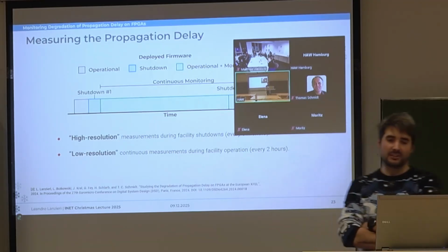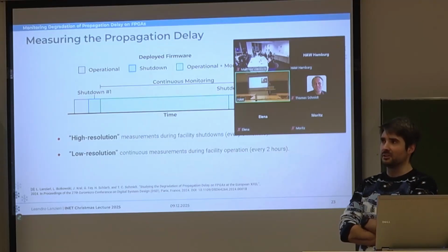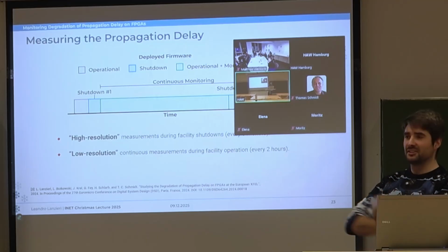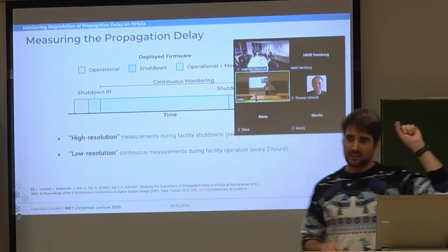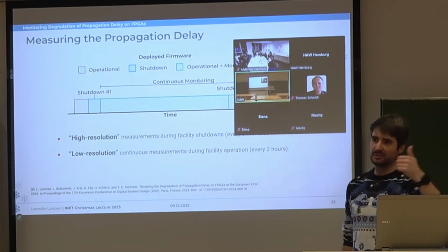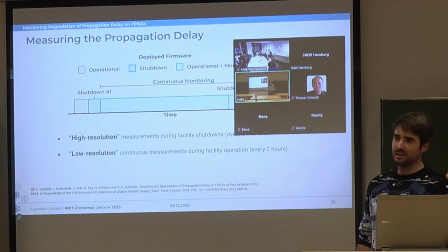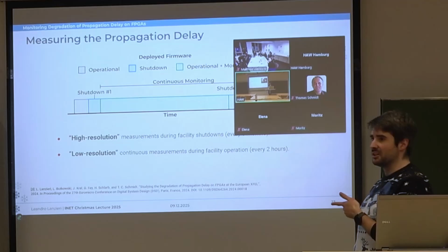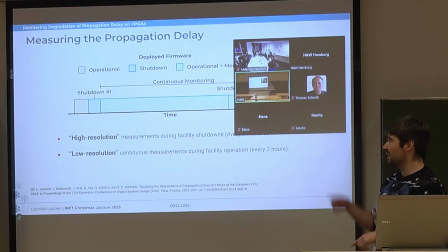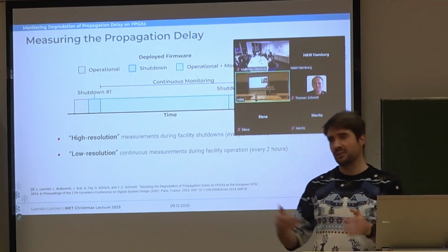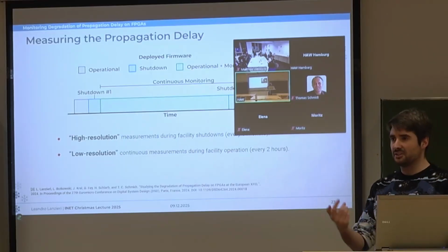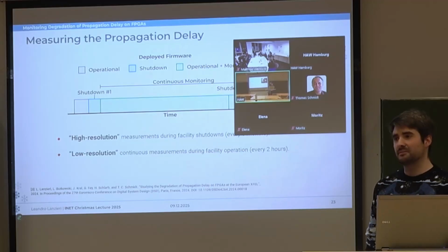Not, I think I understand. And I think if you actually look with a microscope a bit, or more like from far away, this is what we did. If you remember the beginning of the talk, I talked about threshold voltage, and that's actually been the constant across all of the things, because in the SRAM we observe the threshold voltage by looking at the startup patterns. In the FPGAs we see a change in the threshold voltage which affects the propagation delay of the transistors, and in the microcontroller the same happens. So propagation delay changed by threshold voltage, for instance. So yes, that's a known indicator also if you're looking at a specific transistor like normally you do.